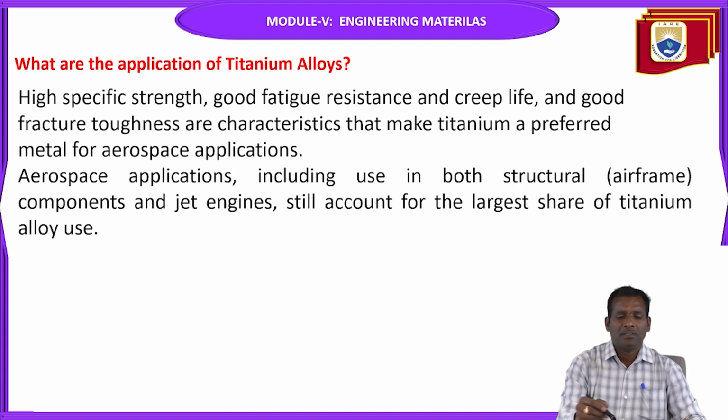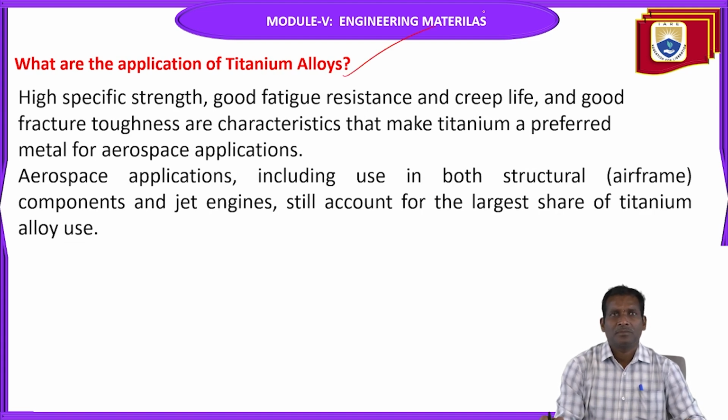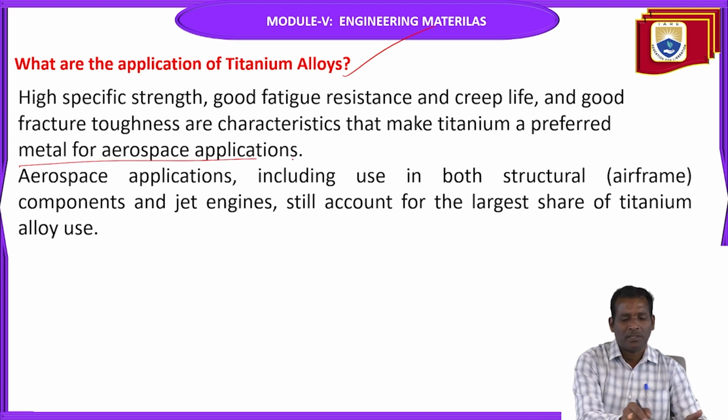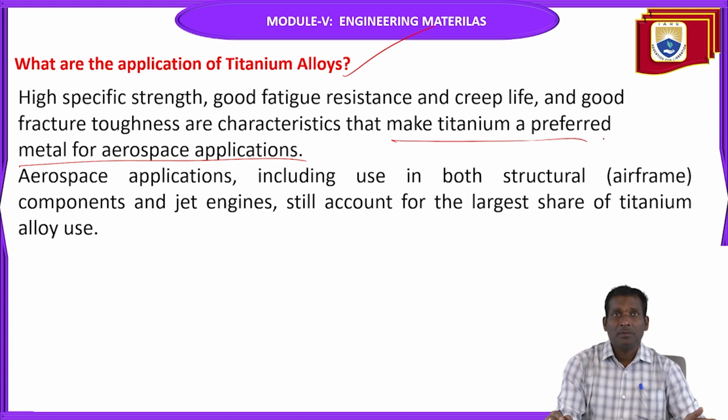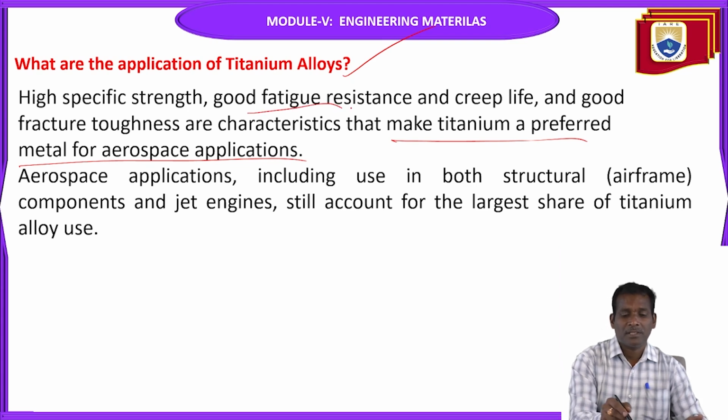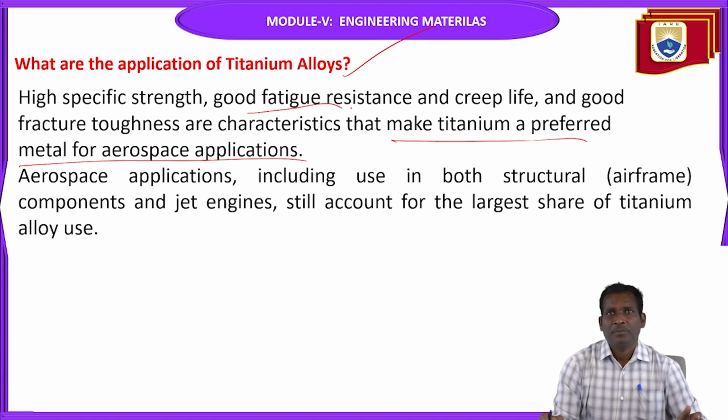So, what are the applications of titanium alloys? Due to the high specific strength, good fatigue resistance, creep life, and good fracture toughness are characteristics that make titanium a preferred metal for aerospace applications. It can withstand high temperatures and has good fatigue resistance. So fatigue is very, very important in the mechanical properties of mechanical components.